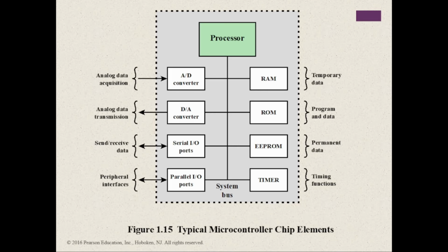Next, the microcontroller chip makes a substantially different use of the logic space available. The figure shows, in general terms, the elements typically found in a microcontroller chip. As we can see, a microcontroller is a single chip that contains the processor, non-volatile memory for the program or ROM, volatile memory for input and output, which is the RAM, a clock, and an I/O control unit.